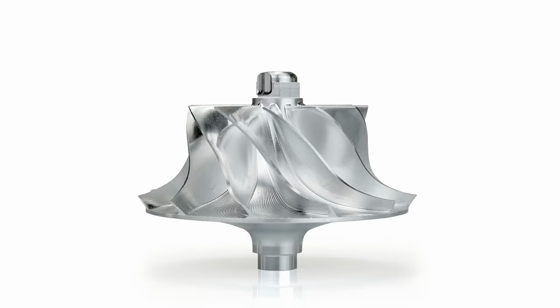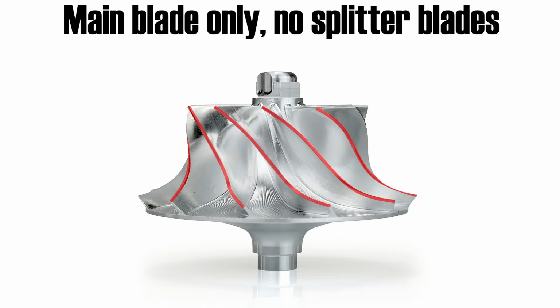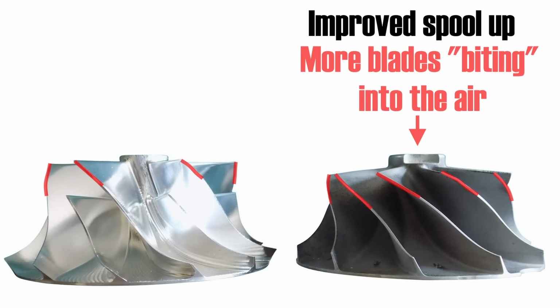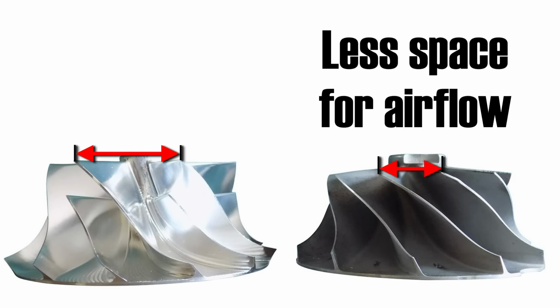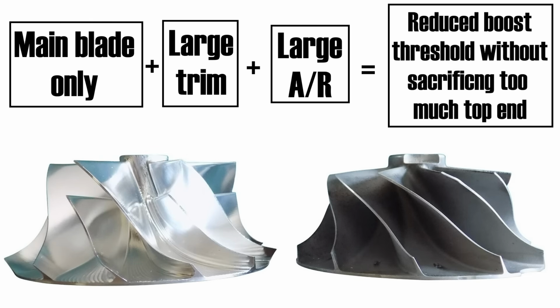On the other hand, aftermarket and racing applications sometimes employ a design that has an increased number of main blades, but without any splitter blades. A design like this improves spool up because there's more blades biting into the air and pushing it into the engine. This design does sacrifice a bit of peak power because there's less space for airflow through the wheel since more of it is occupied by blade mass. But combining a wheel like this with a large A over R and a large trim reduces the boost threshold in a racing application while maintaining top-end performance.